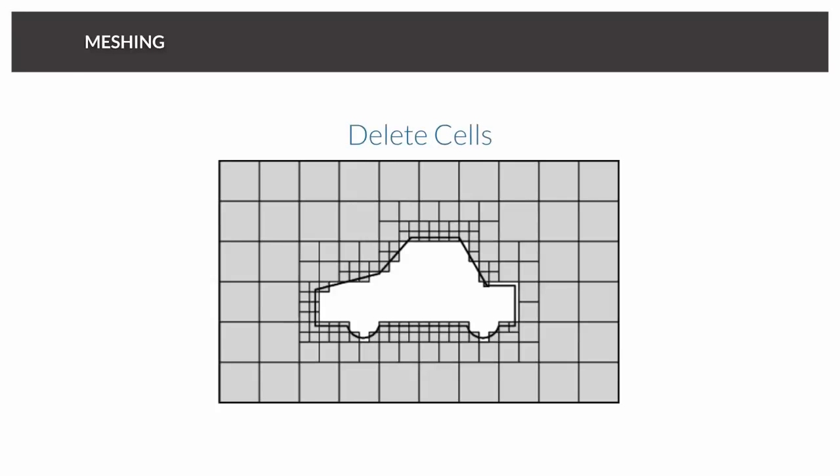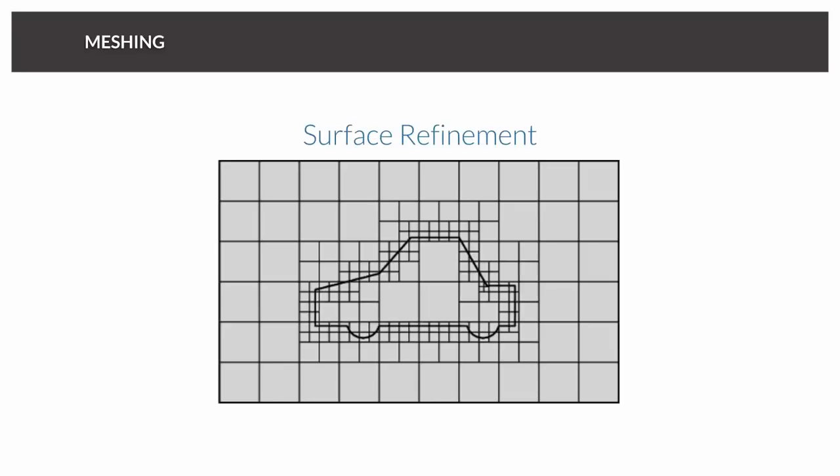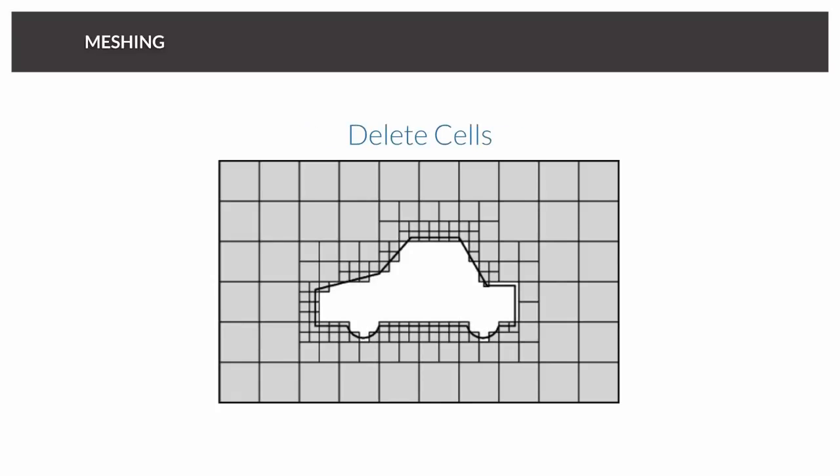And this is maybe the most important step, because now a flow around or flow inside the rectangular pipe or tunnel becomes the flow around the car. Still, we can notice some things. First of all, our mesh looks very steppy, how should I say, it looks like a Cartesian mesh. It's not smooth. And we don't have any volume refinement. That's what we're doing next.